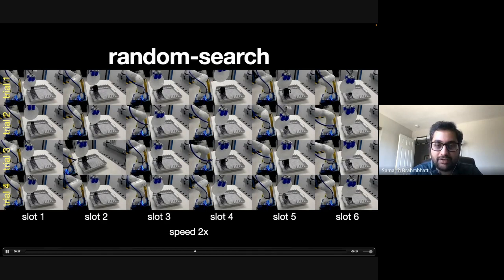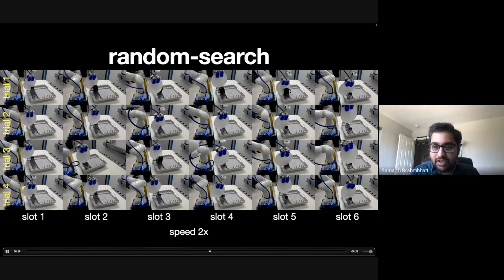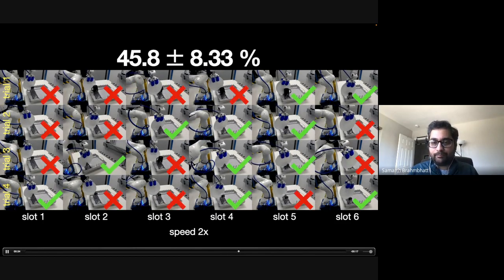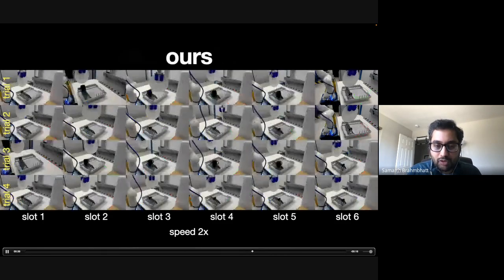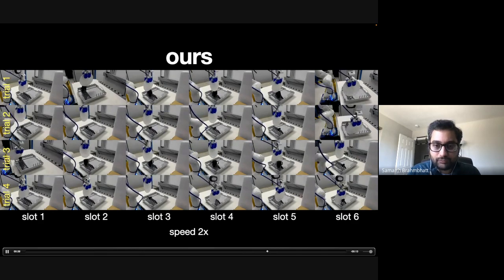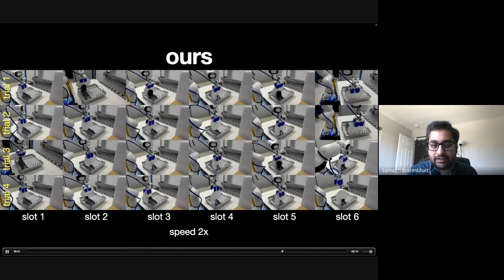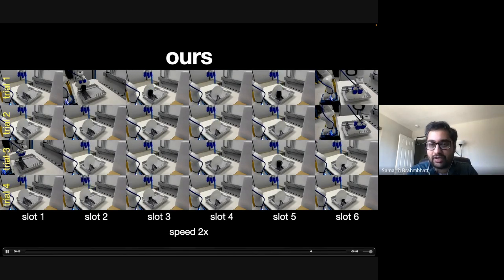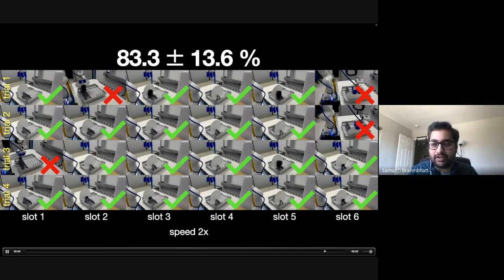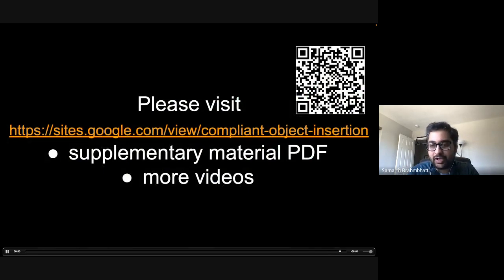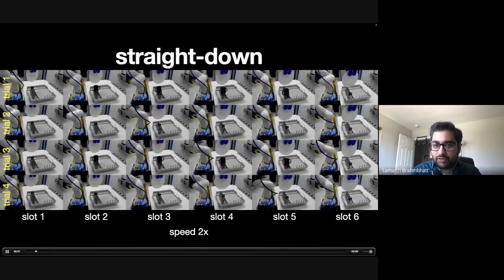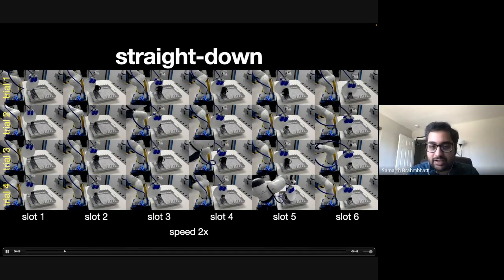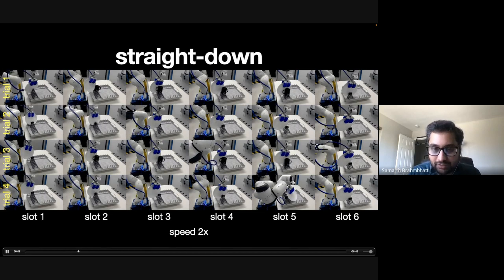Because even if you get a different robot of the same model, it's going to have different joint frictions and inertias, etc. So what happens in this sim to real loop is that you train in simulation, then you try it out on the one robot that you have, and then you fine tune your simulation again to improve it on that one robot you have. But it will work well on that one robot, but when you give that policy to somebody else, just with that same Franka arm, it might not transfer.